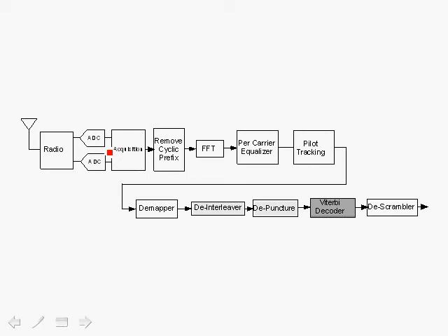For example, on the Viterbi decoder, you can use a larger traceback buffer. You can use a 3 to 5 bit soft demapper. And in the case of equalization, you can be smarter about the way you do equalization and smooth, for example, the channel estimates. You can use higher precision in the FFT. For example, in acquisition, you can do a better job in timing synchronization and, of course, in carrier offset estimation and correction.